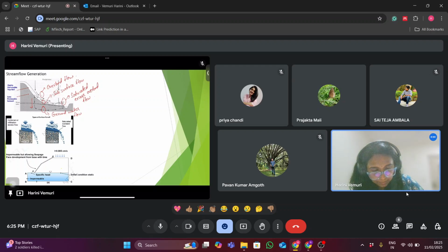So first is infiltration excess, Hortonian overland flow. Okay, so when we neglect interception by vegetation, the surface runoff is that part of rainfall which is not absorbed by the soil by infiltration. This is called Hortonian excess rainfall.